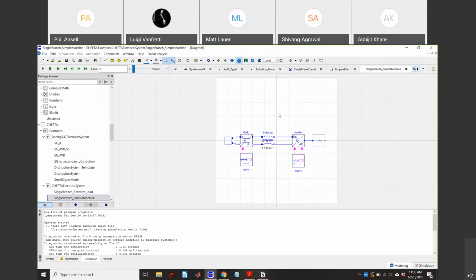And finally, all of those individual controllers that you will have, this PWM, the PWM1, and the other one, imagine that they will be expanded to have the control functionalities they need, and that the motor has another controller. Then the energy management system has to tell them what the references are, for example, of the DC voltage, and on the inverter, it is going to tell it what power needs to be delivered according to the flight controls. So then that would mean that the controllers would need to talk to each other too, is that right?